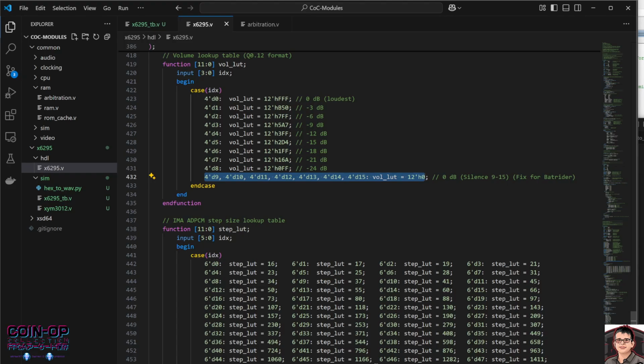You start to get a sense as to like, okay, I was at level 0. Now I'm at 2000 something, and now I'm going down to 1000, or I'm going negative, I'm going below 0. Okay, I'm going higher and lower and higher and lower, like a waveform, right, over time? The time unit described is called the sample clock. So the sample rate is how many samples per second would lead to that waveform being constructed, right? So you iterate through everything at the sample rate. You output samples at the sample rate.